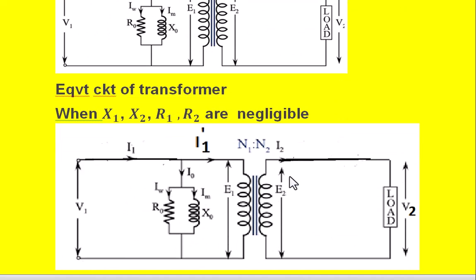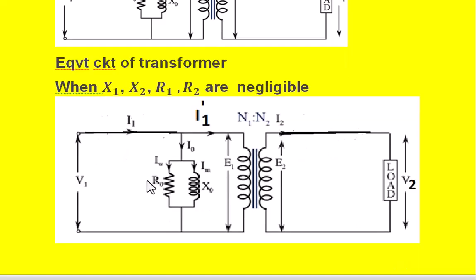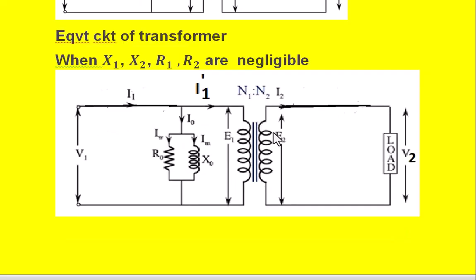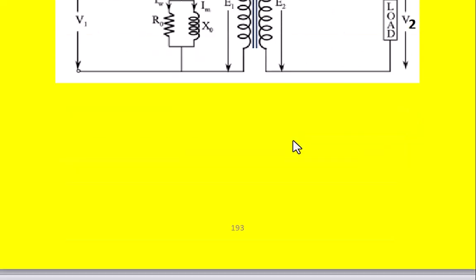So here no R1, X1 business. Similarly, there is no R2, X2. Means just we short circuited that. Once that is done, we find here the primary applied voltage is V1 or VP, and input current is I1 or IP, and the no load current is I0, and I1 dash is the primary current component corresponding to the secondary current I2, and remaining terminologies as usual discussed earlier.